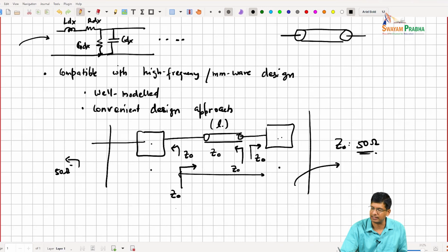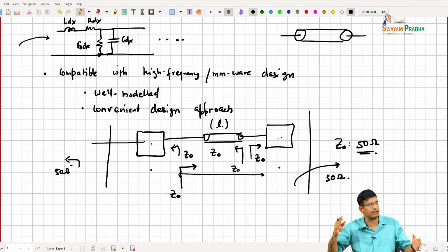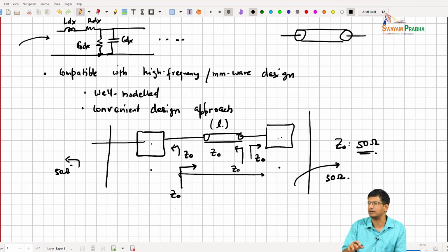And then let's say that you're feeding this to a piece of equipment to analyze it, like a spectrum analyzer or network analyzer, that is typically 50 ohms as well, right? So when you're bringing your chip, then you have to consider being matched to 50 ohms, but it doesn't have to be necessarily matched to 50 ohms inside your chip.